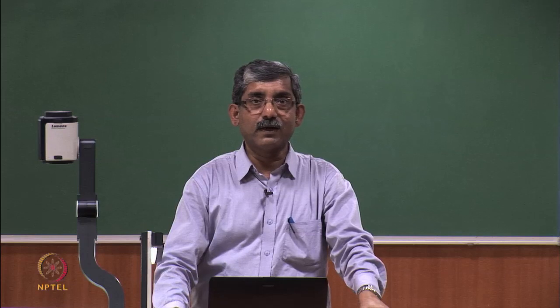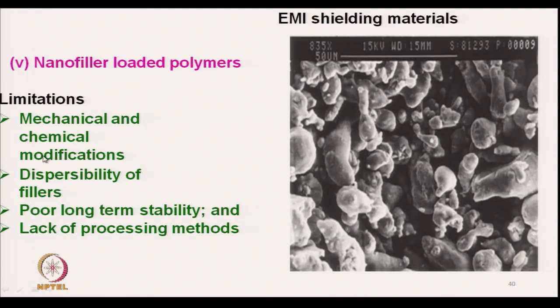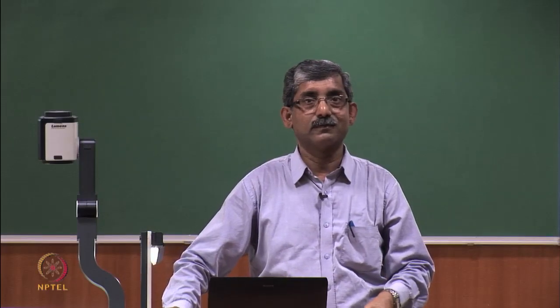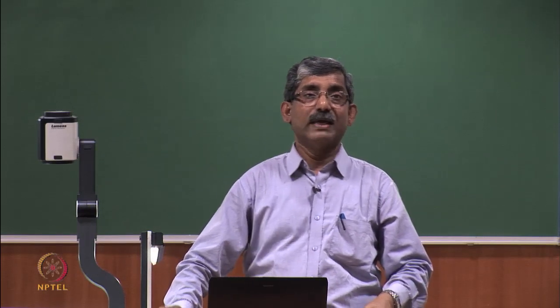But the main disadvantages of these nanofiller loaded polymers are mechanical and chemical modifications, and the dispersibility of these fillers. They are not dispersed easily, agglomeration may take place, and one should take care of that. There is also poor long term stability and lack of processing methods. So, these are the problems, and then there are conductive fabrics, which are the best solution,